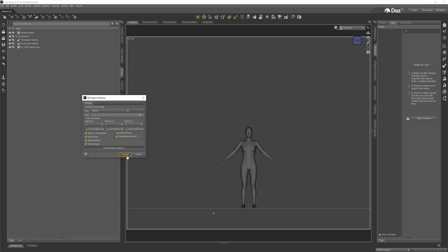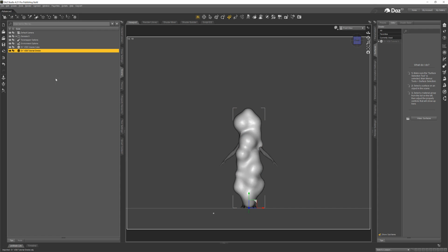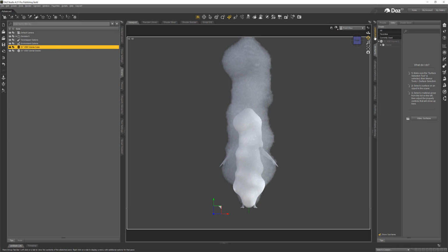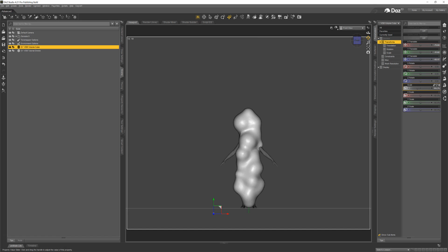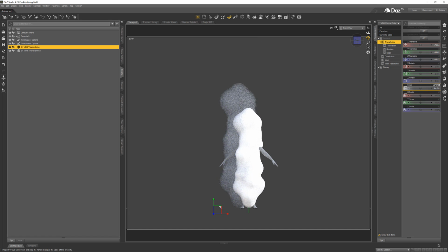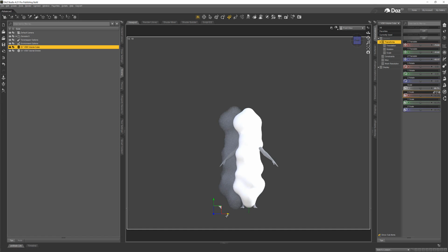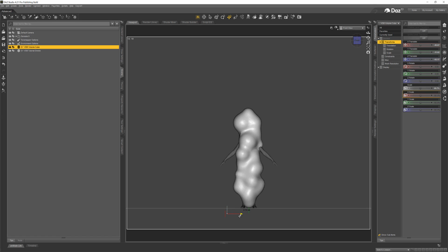I'm going to leave that at 100% there. There we go. You can see that looks a bit small, so I'm probably going to need to scale and position the volume cube to fit inside that, and then I can rescale that to whatever size I want it to have in my scene. So what I'm doing now is scaling and positioning the volume cube to match up the scale and position of that proxy, or I could go back to Blender and make the proxy bigger. That's another option.